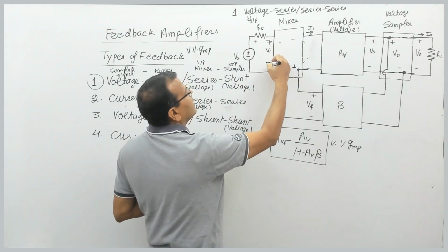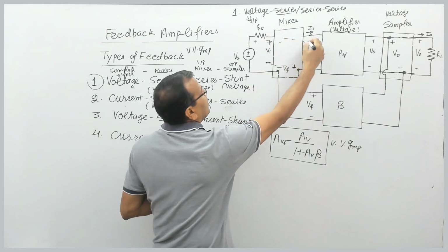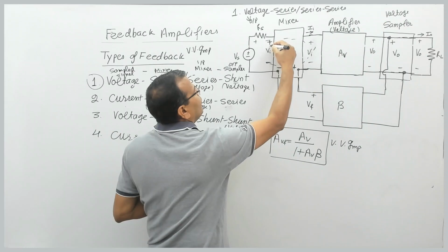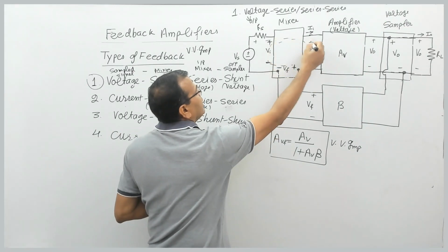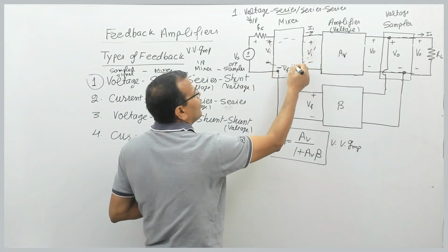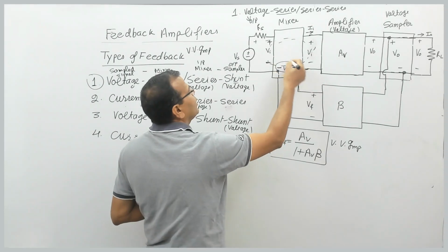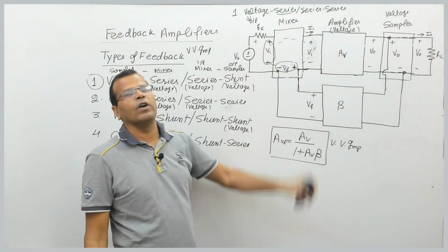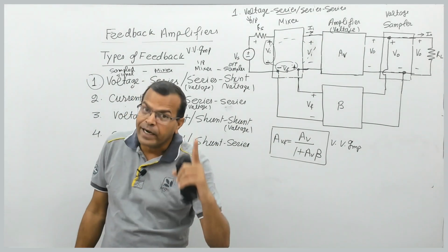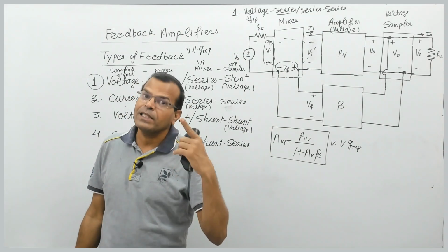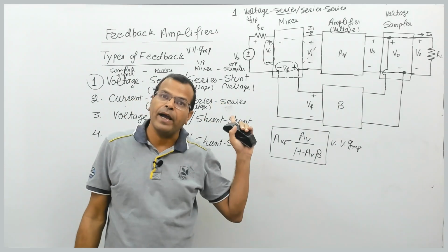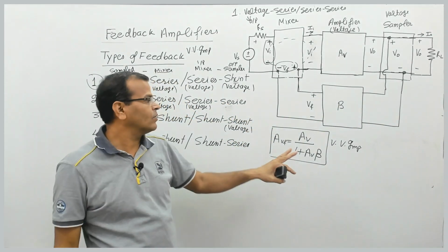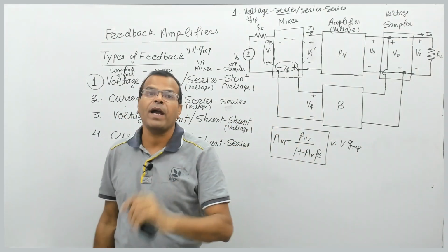If you come like this, this is a voltage rise. Come like this, say this is VI dash, right? VI, so voltage rise, then plus minus, voltage fall. So this voltage opposes this voltage. If it is voltage rise, it is voltage fall. So feedback is negative. When the feedback signal opposes the input supply, then this is known as negative feedback. So this amplifier has negative feedback.